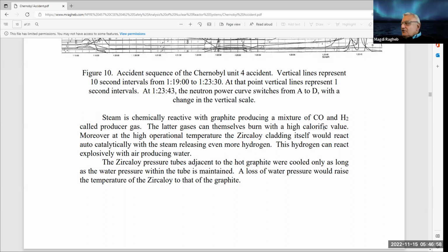And the high temperature of the zircaloy cladding itself can interact with the steam. The reaction of hot steam with any metal, as you all know, is this. If you bring in steam, H2O, on top of hot iron, you'll find that you oxidize the iron. You burn the iron, literally, it becomes iron oxide, and you release hydrogen. In the case of those reactors, they use zirconium as an alloy. So in that case, you oxidize the zirconium to zirconium oxide, and you release hydrogen. So look at all the sources of hazards now if things are not occurring as expected or as designed.